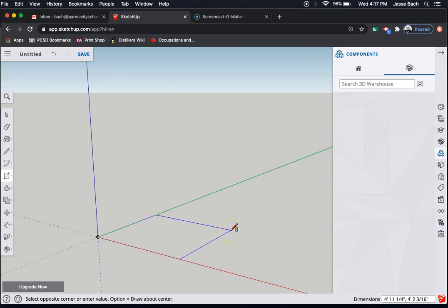So what we have to do is change this to 3/4 of an inch square. So I am just going to enter 0.75, that is 3/4 of an inch, hit comma, space, 0.75. And if you look down here, that's where I entered it. Let me show you again. 0.75, comma, space, 0.75. Now when I hit enter, you're going to think that you did something wrong because this rectangle is going to look like it disappears. It doesn't disappear. It just becomes 0.75, 3/4 of an inch.